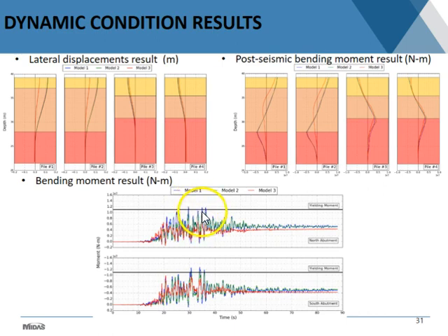And this is telling you that inertial forces are important. It's not only that you have liquefaction and the tendency to have lateral spreading, but also the shaking is relevant in this type of situation. So the concept of trying to do a decoupled and really simplified analysis, even for this case, which is a simple one, a short bridge where you have only one layer of liquefiable material, even in that situation you may have issues like the one that I'm showing right here.